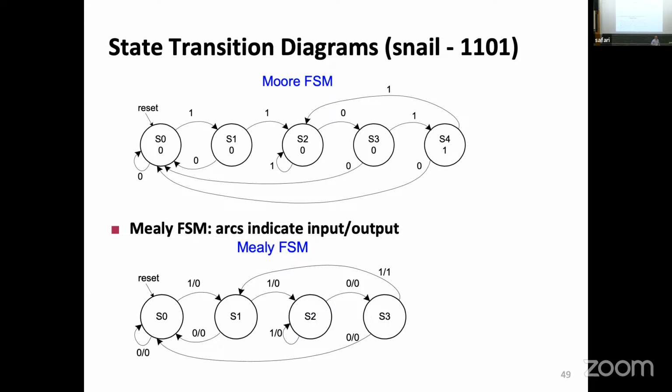Yes? Copy? Yeah, we don't need to do it differently from Mealy. We could also do that, yes. We could. Well, let's not ignore the input. The input would move me to the next state. When I'm talking about the output logic, you can just ignore the input in the output logic. Well, if I ignore the input in the output logic, I'm making a Moore-type state machine, and I end up with that one. Yeah, but it still has the same circuit as the Mealy.